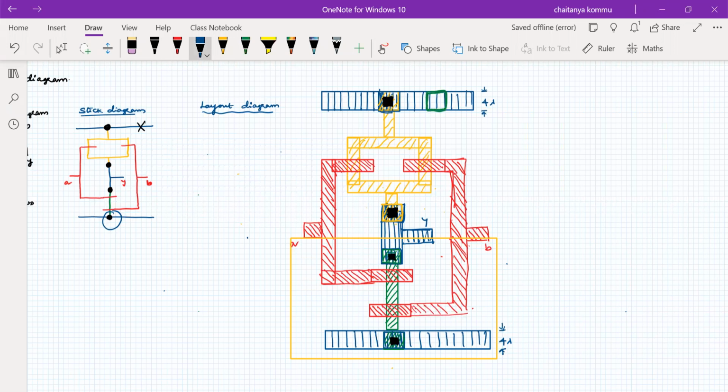Similarly, I have to consider the metal lines also. And we have to use the metal contacts. The contact cut is required there. Similarly, we need to provide the P substrate for the NMOS transistors. And I'm going to consider these things. To reduce the time, I don't want to use the hash lines more and more. So please remember that it's 4 lambda by 4 lambda. Okay, so contacts are also clear.